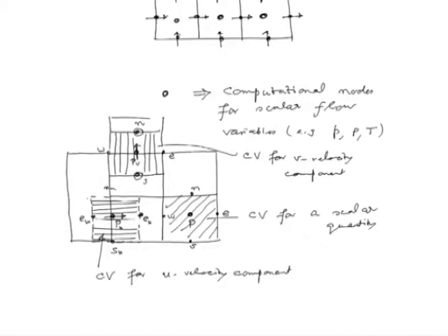that traditionally what we think is that the velocity field or the flow is driven by the difference of pressure. So, the velocity at any node is because of the pressure difference at the adjoining two computational nodes. So, that is why this particular grid arrangement gives us what we call very strong pressure velocity coupling.